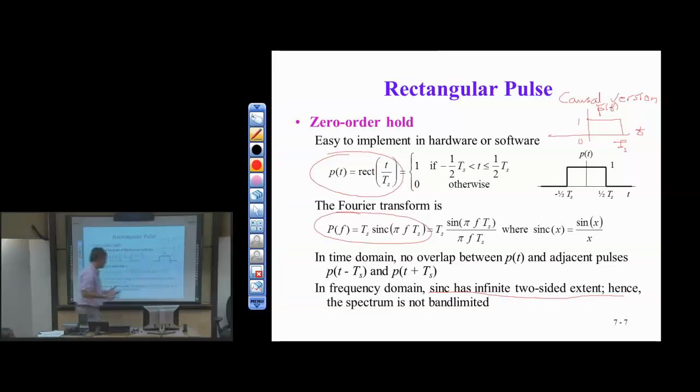So what do we do? How do we fix this? And this is our discrete time to continuous time conversion block. So what comes next? An analog low-pass filter to clean up, to get rid of all these frequencies that are above half the sampling rate. And we've got a lot of them. We have a sinc here that just keeps going out to infinity and minus infinity, decaying slowly with frequency, 1 over f. So here's the decay rate. Very slow decay rate. Its frequency goes to infinity.